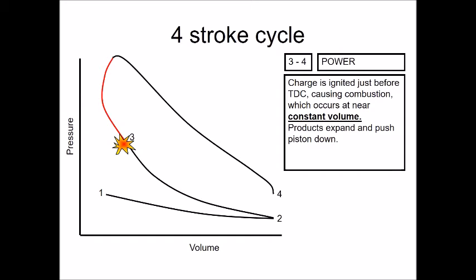Okay, there we go. So I coloured in part of it red because that's symbolising that the chemical reaction called combustion was taking place, and then the combustion kind of finished, but the gases are still hot, so they're still pushing the piston down. So we can see we're at 0.4 now, and what is ready to happen is that one of the valves can open now. So the exhaust valve is going to open. So from 2 all the way around to 4, all the valves were closed, and now it's time to open up the exhaust valve and let those products of combustion out of the cylinder.